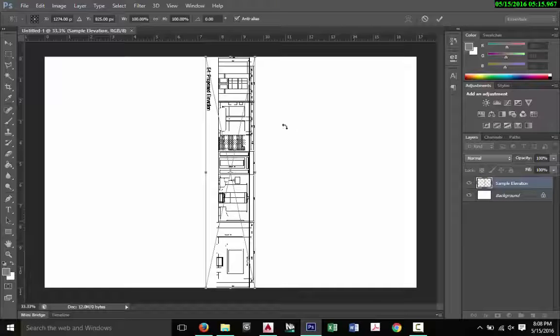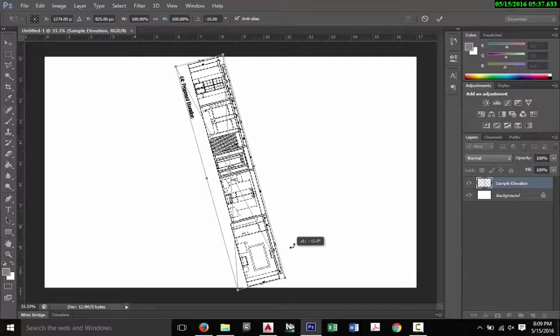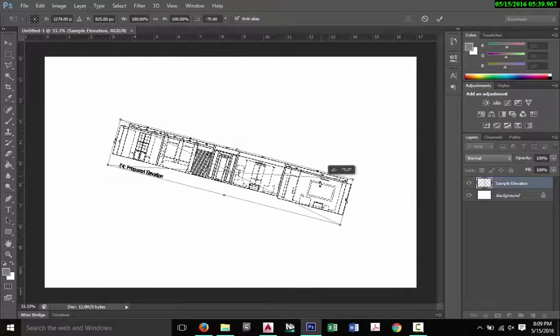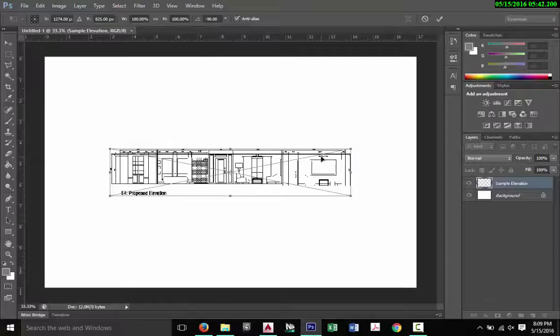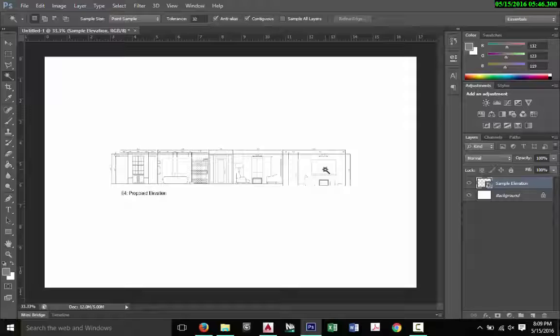It will almost always place this in the wrong direction. So a good little trick to know is how to rotate this with an orthographic lock so that you're not getting a rotation that isn't straight. By default, we've got this little rotational cursor going on here. So if you hold down the Shift key and then click and drag your mouse, you can rotate this and see how it's locking. It'll lock to a 90-degree rotation and say OK.